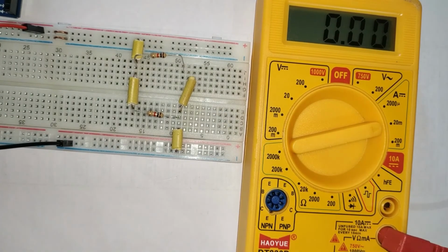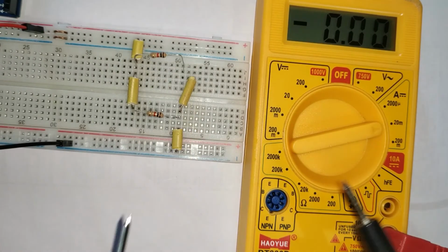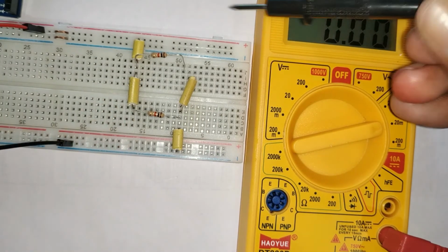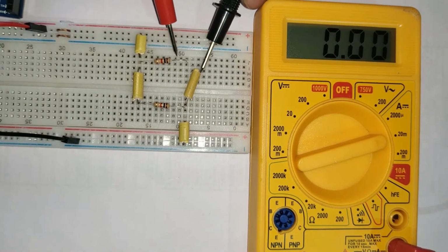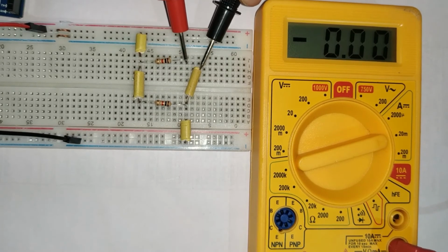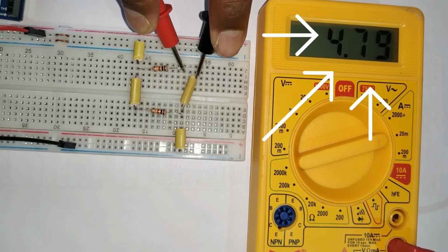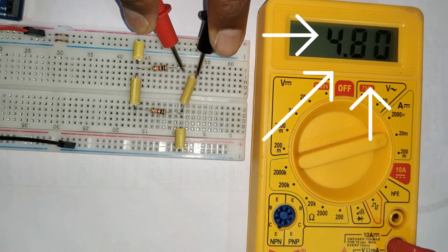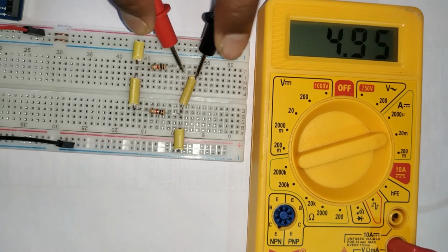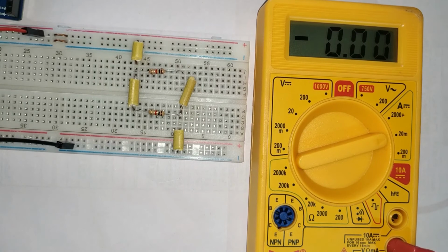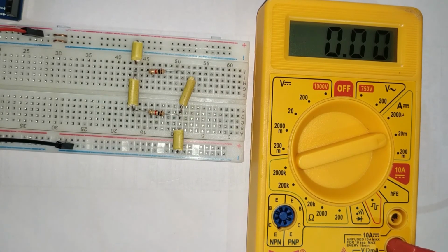We will place one end of our multimeter to the resistor and another to the wire, so they will complete our circuit. Now you can see I am putting one end to our wire and another end to our resistor. We are getting a current of 4 point, it's fluctuating but around 4.8. Total current was about 9.8, so this is close to 5 milliamps. As we theoretically saw, both resistors will carry 5 milliamps of current. So we are getting the first resistor carrying 4.8, and that is close to 5 milliamps.